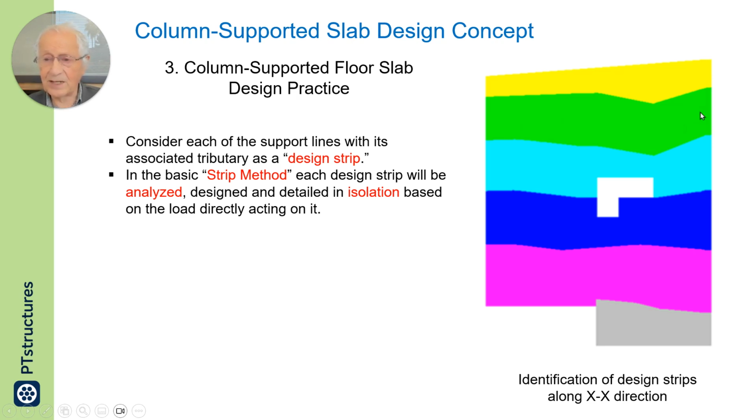prescriptive method is concerned, load which is on a given design strip will be carried by that design strip, will not be shared. The question of sharing is implicitly addressed when you go to the up-down design strips, because you later do the same in the orthogonal direction, once in one direction, once in the other direction. The other direction will take care of the item that I just raised.